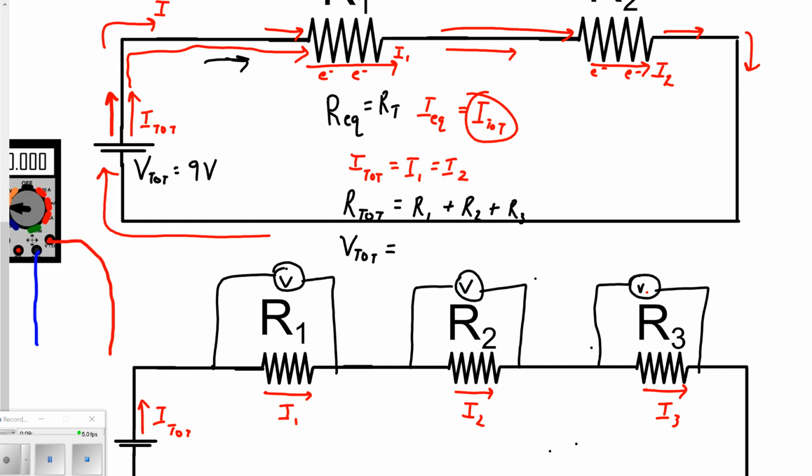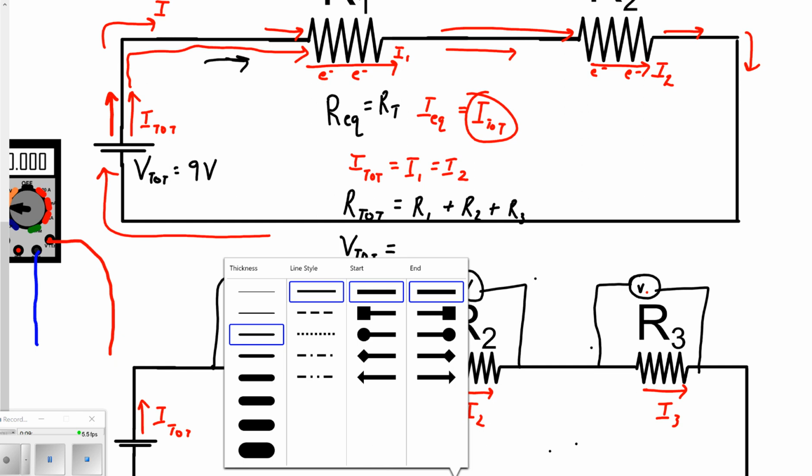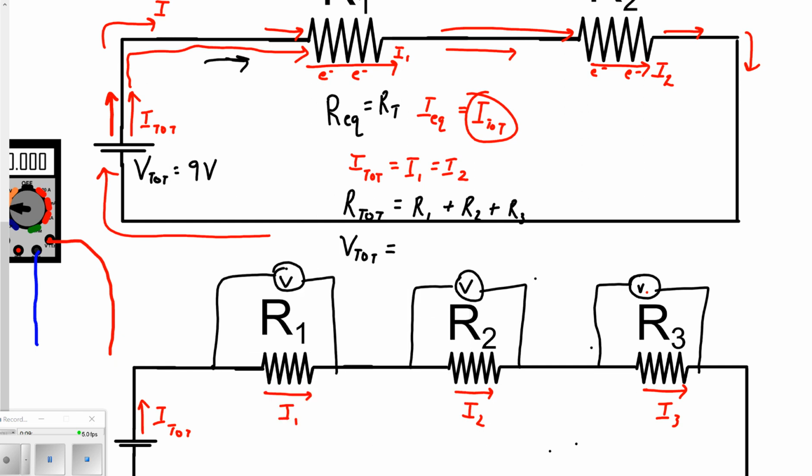All those potentials would combine. Let's say, for example, if it was like this one up here that had the 9 volt on it that we looked at earlier, all of the potentials would combine to make 9 volts. And so what you would also find now is this. Our formula would be V1 plus V2 plus, here we'll say V3, would all equal V total. And we could have R3, R4, R5, and we could just keep going with the resistors out through here, and this would still hold true.